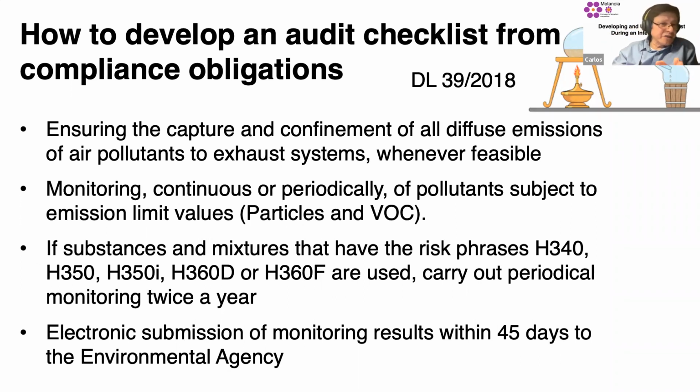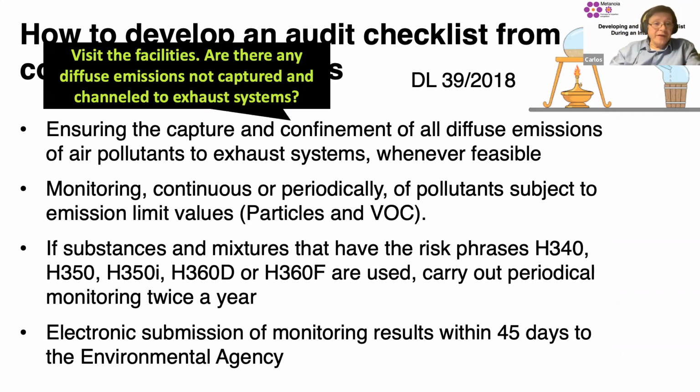If substances and mixtures that have these risk phrases are used, carry out periodical monitoring twice a year, and then electronic submission of monitoring results within 45 days to the environmental agency. So what can we do with this? It will be something like this, the kind of question. About the first topic, visit the facilities. Are there any diffuse emissions not captured and channeled to exhaust systems?